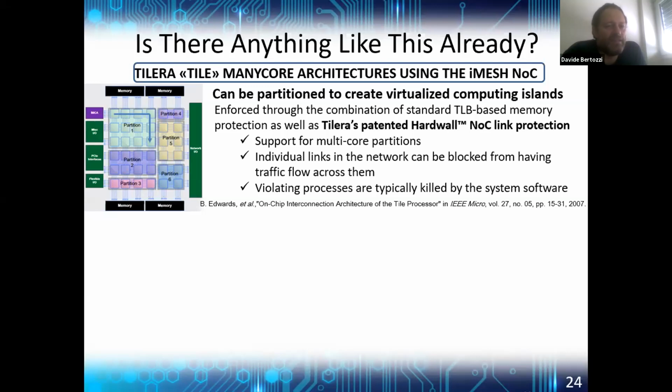So you can identify computing islands, and you can have your own operating system running inside the partition with its own applications. The isolation between these partitions is achieved through Tilera's patented hardwall network-on-chip link protection scheme. With this hardwall protection scheme, individual links in the network can be blocked from having traffic flow across them.